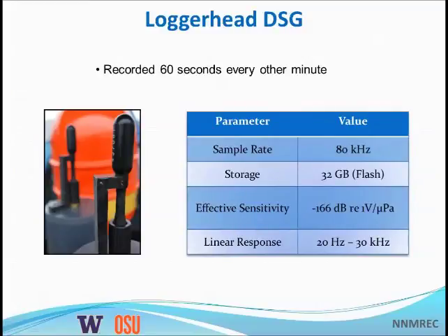So the loggerhead itself, throughout these recordings, operated on a continuous sampling cycle for 60 seconds every other minute. The sampling rate was 80 kilohertz, and this device is essentially a pressure case with mostly space for battery storage. And then there's a small data acquisition system located in the pressure case as well, and it takes just a flash card and connects directly to the hydrophone. So it's a totally autonomous system, which allowed us to deploy it on the spar buoy.